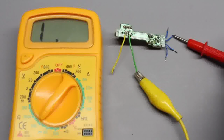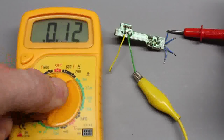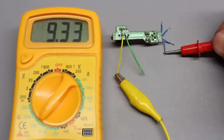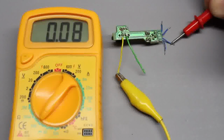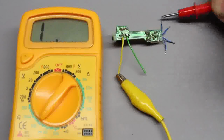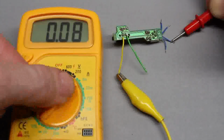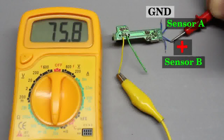The cathode is usually joined directly with ground of the supply voltage. The reading will be very close to 0 ohms. The minimal reading of the second path is 75 ohms, which is caused by the series resistor between plus of the supply voltage and anode of the LED. The cables left are those of the sensor outputs.